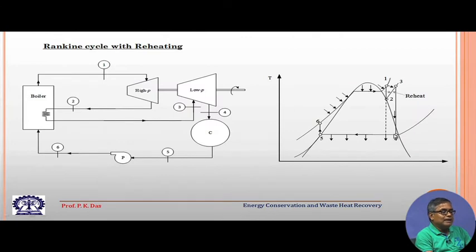If we go back, we can see that this is an isentropic process. So, this entropy S4 will be equal to the entropy at state 3. So, for state 3 now two conditions are known. We know the pressure, we know the entropy, and obviously it will be in the superheated region. So, this point is now fixed on our thermodynamic plane and we can calculate any other thermodynamic property.